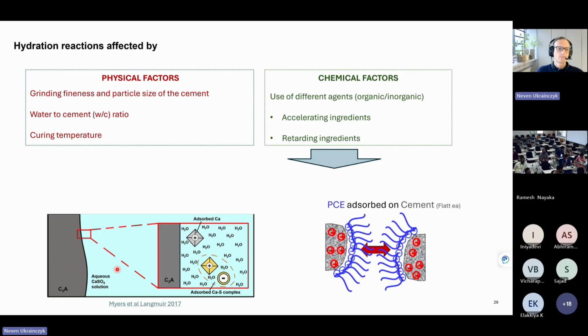It really comes to the civil engineers at the end that you need to know this chemistry stuff. Because when you do LC3, so the limestone calcined clay mixture, I would suggest you do the calorimetry and check of the cement paste, and then check the peak, and then you can optimize the sulfate addition. Much easier than doing compressive strengths, for example.